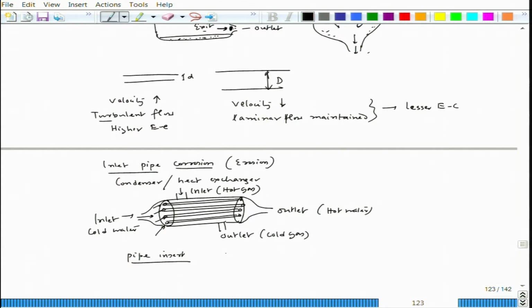So, the pipe insert looks like this, fine. Now this insert is actually taken into the heat exchanger pipe. It is inserted quite deep inside, close to 25 to 30 inches. Okay. So, that is the distance one tries to take. So, this is not that much, it is around 6 to 8 inches. So, that is the level of insert distance or insert length.